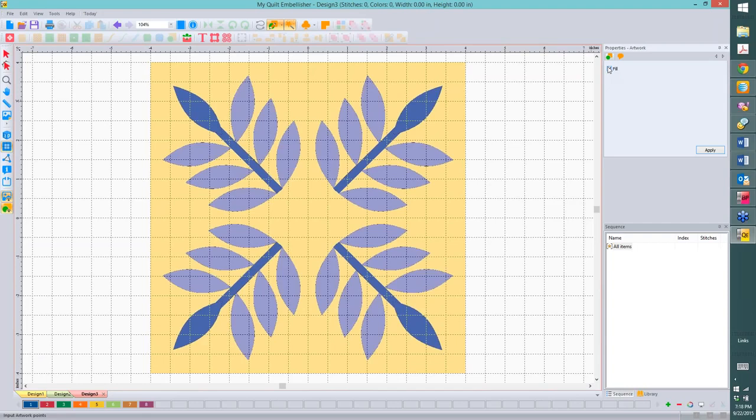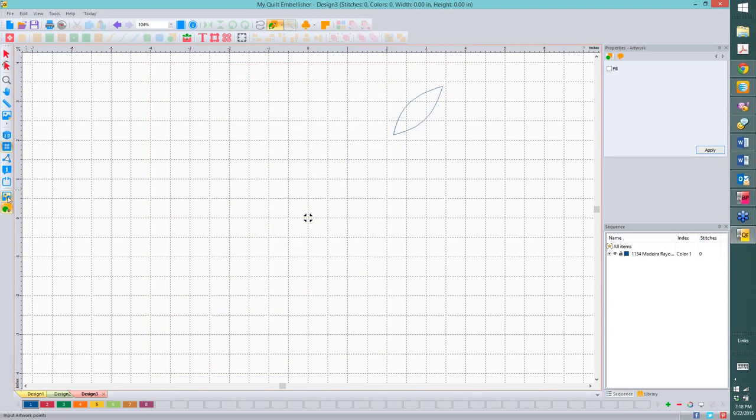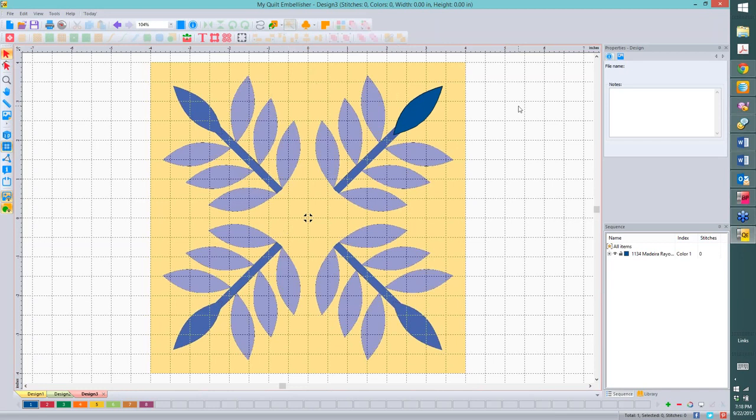because the outlines are sometimes hard to see. So if you know you've done everything right, and you've clicked on that, but you don't see it, here I'll show you, turn off your backdrop over here and see how that's not filled, so it's difficult to see. If you fill it by selecting it and clicking fill, then you'll be able to see it. Let's turn our backdrop back on. But I prefer to have it be filled from the start. So I select it again, and I click fill before I ever start creating my leaves.